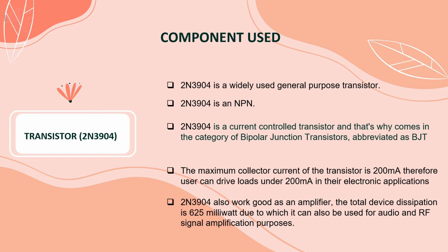Next, the maximum collector current of the transistor is 200 milliampere. Therefore, you can drive loads under 200 milliampere in your electronic application.